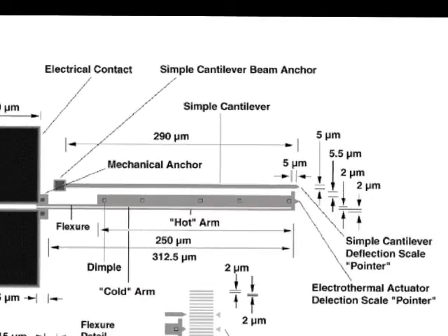Here are some of the design specifications. And you can vary this a little bit if you want. Instead of 2 microns, you can make it 3 so it doesn't break design rules. The idea, though, is try to make this length the same as what's written here. Okay?